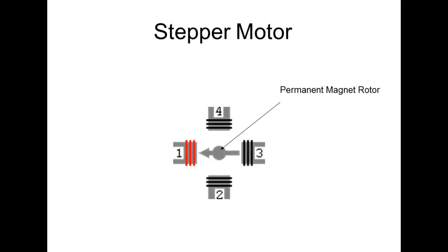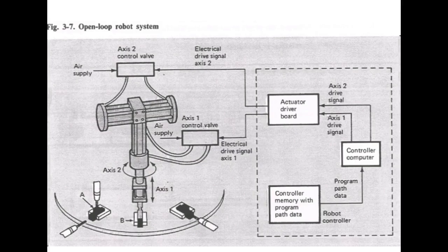They're really cool. And we've got one on our Amatrol line over there that's positioning a carousel, and it's a stepping motor. We tell it to move once it finds its origin, and we'll show you how it finds its origin. Once it finds its origin, we can tell it to move 90 degrees. Well, we don't tell it to move 90 degrees. Our computer would take 90, divide it by the number of steps, and send that many pulses.